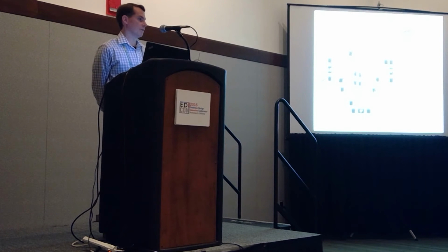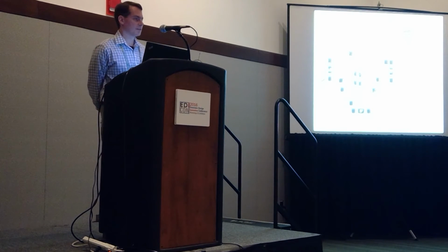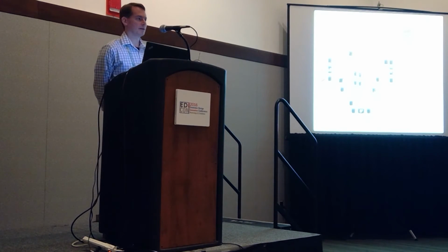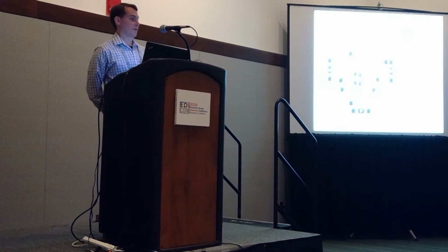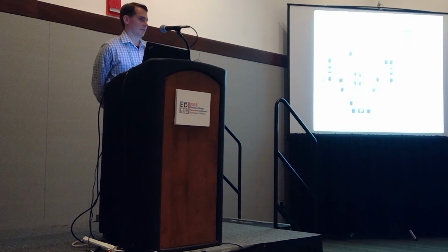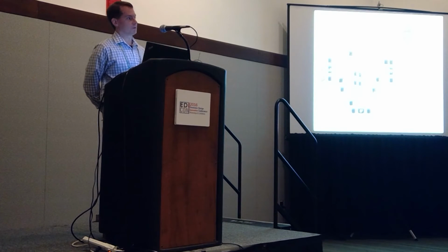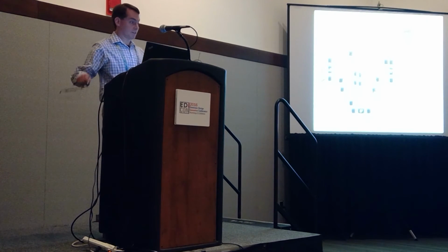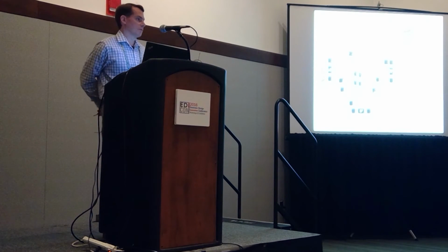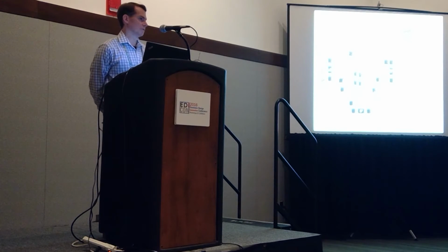We got the bandwidths that we wanted. The IP3s actually came out a little bit better than we had simulated, certainly for the FET mixers. The problem with the PDK is we're not allowed to look at the FET model. It's just a black box, so we're at the mercy of what the foundry did. The foundry had made the models for power amplifiers, and we were using it as a mixer. It gave us the bandwidth very well, but the IP3 simulated a little bit lower than we measured. So that was a nice surprise.